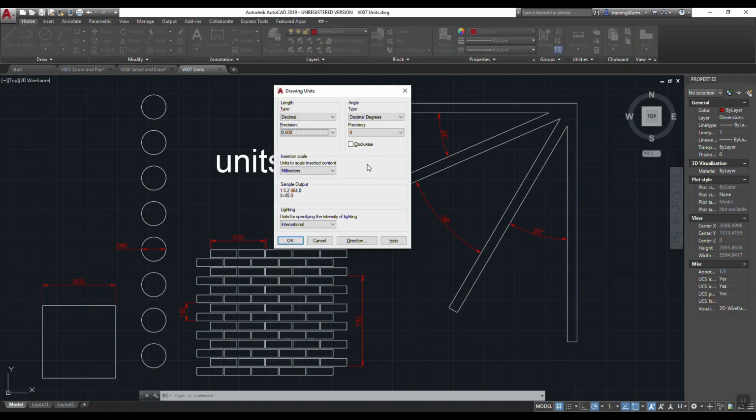And you'd go, oh, that's 12.4. I need to maybe tweak that a little bit. But if you've got it set to 3 decimal places, you will see precisely that it says 12.360. And therefore you'll go, oh, that actually is nowhere near what I really meant. I'm going to have to redraw. So you've got this way of having self-error checking.